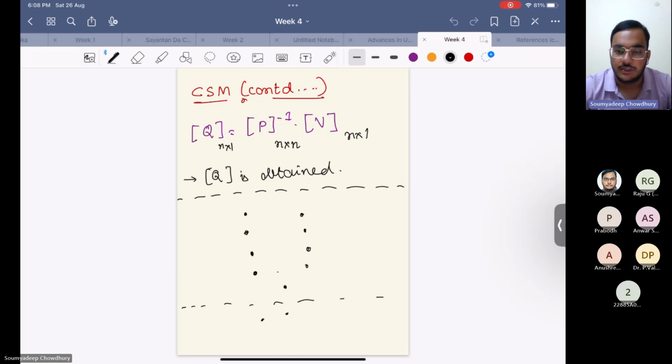It can be point charges, line charges, or ring charges. The type of simulation charges depends upon the geometry of the system. If you have an axisymmetric system, that is a geometry which is symmetric about a particular axis, we generally use ring charges, or for a straight conductor geometry, we can use point charges also.